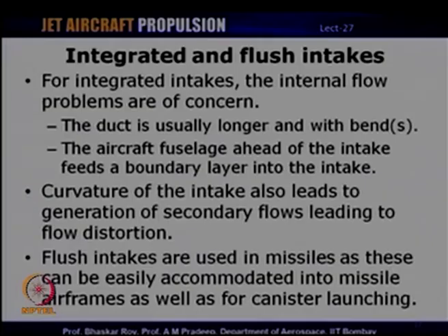Besides this, the intake usually gets its air from the fuselage surface, which means that if there is a boundary layer developing on the fuselage, that boundary layer might feed into the intake, and therefore the intake entry itself would have a non-uniform flow, which might get amplified by the time the flow leaves the intake.